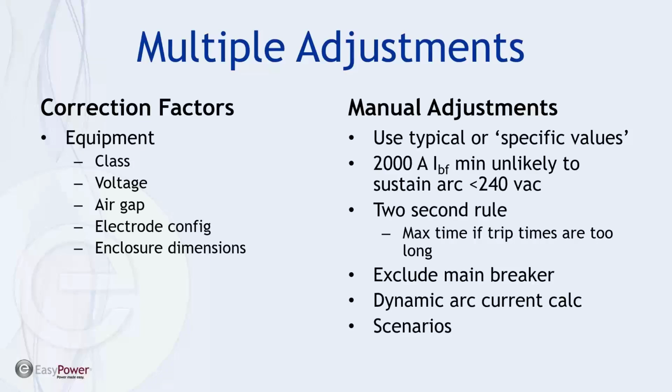When it's closed up, as long as it has been installed and maintained per manufacturer's instructions, the arc flash boundary technically does not exist. So the problem is when we open up that door, or we open up that panel cover, we are exposing an individual to the potential for arc flash, and so it's vertical in an open box. Appreciate the difference.